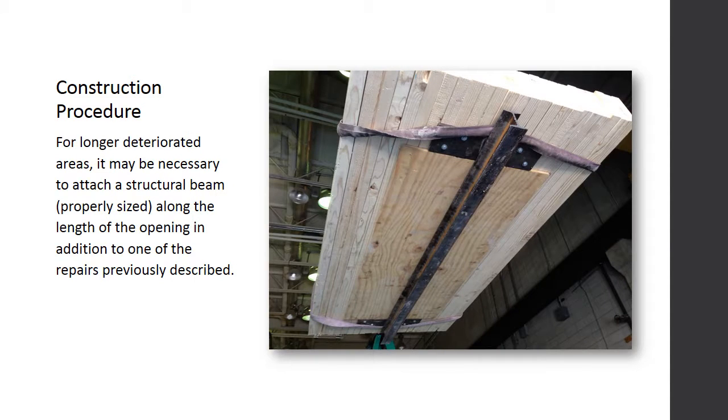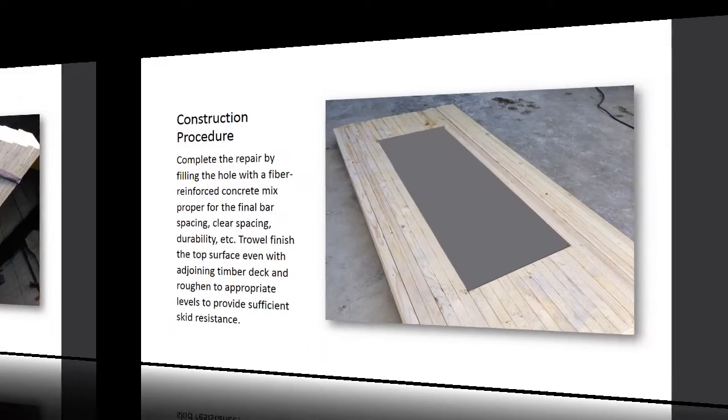For longer deteriorated areas, it may be necessary to attach a structural beam which has been properly sized along the length of the opening, in addition to the repair steps already described. In any case, a beam would be helpful to provide additional support and strength for little additional cost.